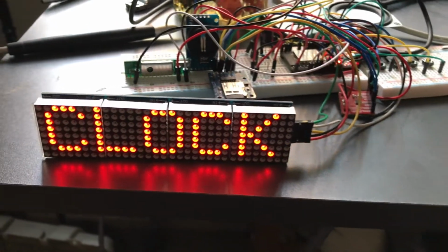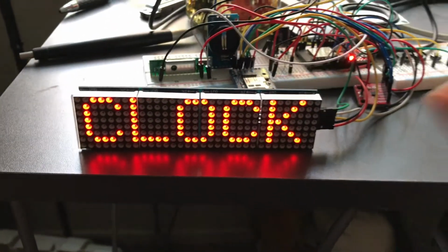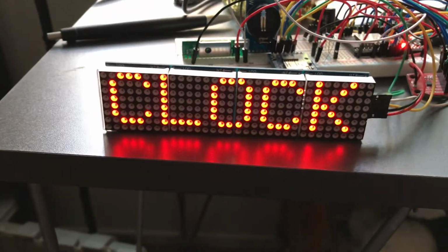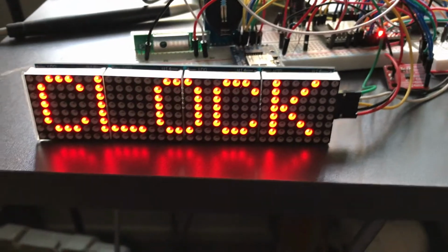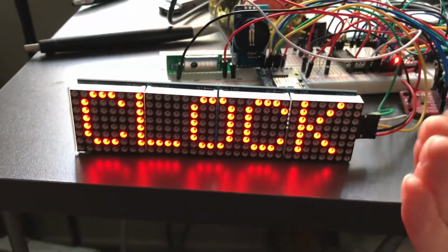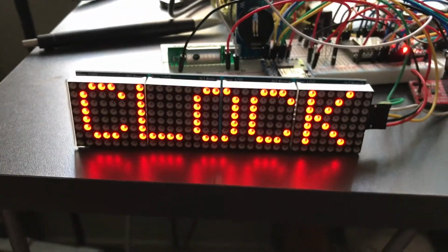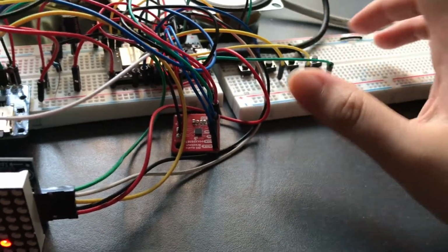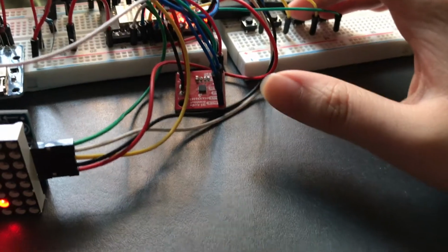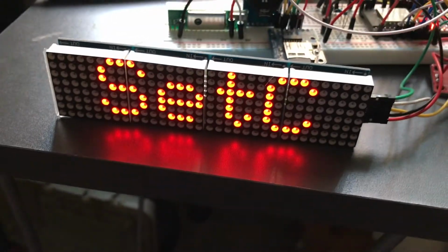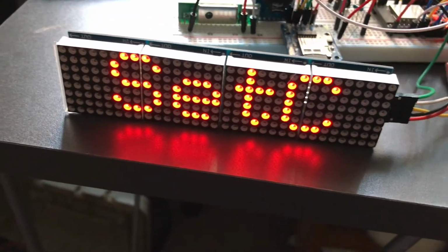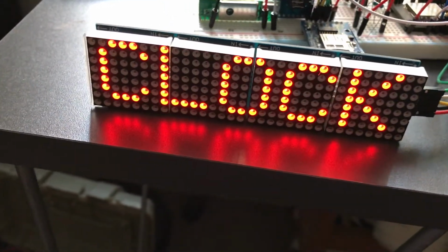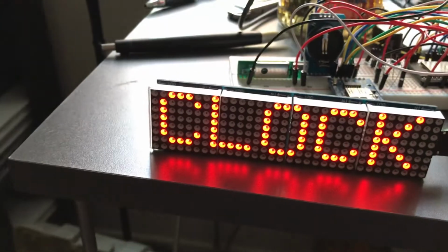Alright, let's walk through how this is supposed to work. Obviously, not everything is fully programmed, but at least the state machine is working. So we are in clock mode. This will display the time. Let's say I wanted to set the time, so this would represent the horizontal axis, the left and right buttons. I would just hold these down for 2 seconds, and then it would go to the set clock mode, and after a timeout, we'll go back to clock. This timeout will be based off of inactivity.